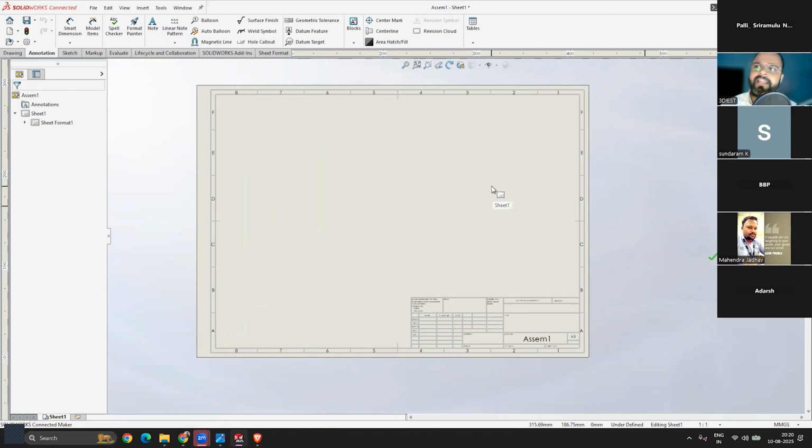If your printer cannot use or print on A3 paper, only capable on A4 paper, then select the A4 paper size. So here I selected A3 because engineering drawings are generally printed on A3 paper sizes. So here you can see, now what we have to do is onto the top, here you can see a new tool panel just got added that says drawings, right?